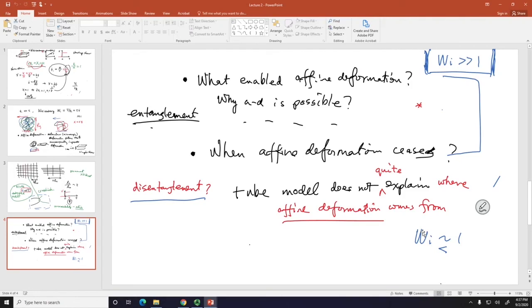So obviously, no matter what you do, the polymer was unable to move because of what we said about reptation: that the tau is such a strong function of molecular weight. It tends to have a big tau. So the polymer is unable to move because they live in a tube.